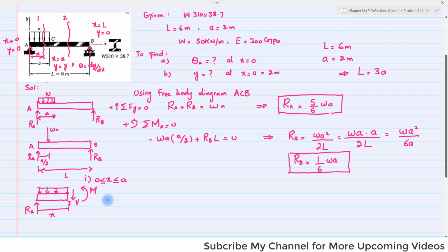We will apply the equation that the sum of all moments about point J is equal to 0. You can see there is a reaction moment M acting, which is equal to M, and there is a moment due to RA into x, and it is clockwise, so it will be minus RA into x.